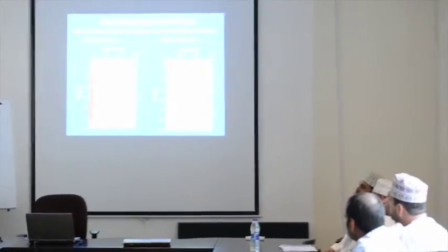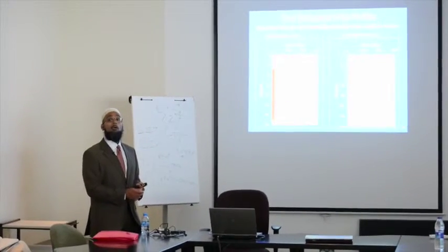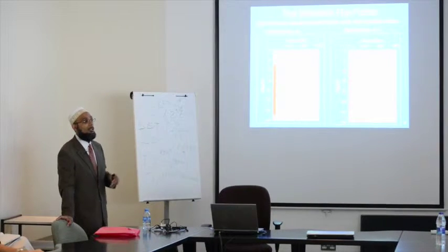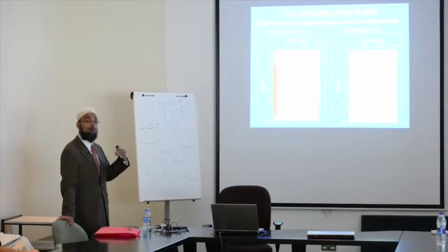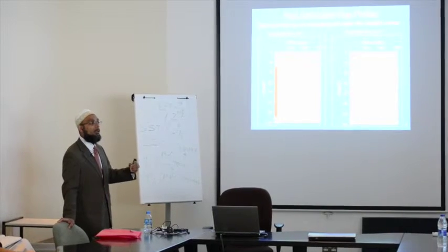So you have worsened the problem the next time you come around. So you have zone 1, high perm, stimulated, and low pressure. So you have multiplied your problem and made it a lot worse by not addressing the stimulation design correctly, right?